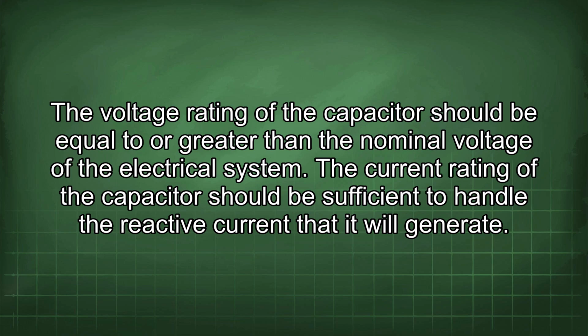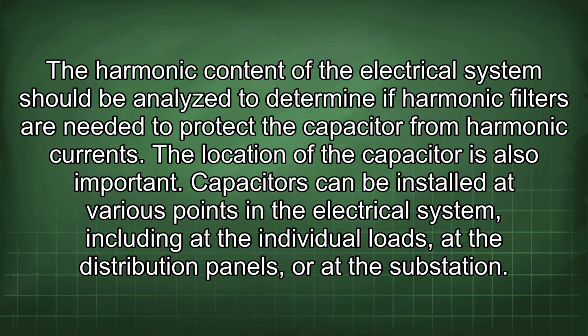The current rating of the capacitor should be sufficient to handle the reactive current that it will generate. The harmonic content of the electrical system should be analyzed to determine if harmonic filters are needed to protect the capacitor from harmonic currents. The location of the capacitor is also important.